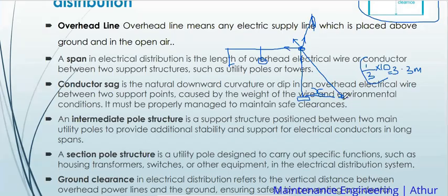And in instances where a person refuses, that he doesn't want much of his area to be filled with this structure, we use what we call an outrigger stay. An outrigger stay has an outrigger bracket. It is always a triangle like this one, but inverted on a pole.